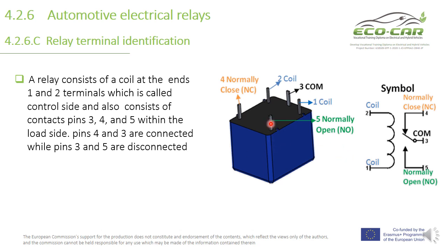This is the contact. This is 1, and this is number 2. There is a coil between these two terminals, while 3, 4 and 5 are the load side.